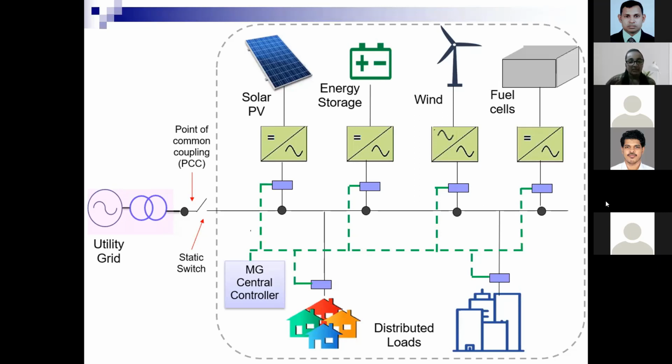And we know when it comes to the conventional grid, large rotating machines introduce inertia to the system such that it will provide extra time for the system to get stabilized in case of disturbance. Since microgrids comprise renewable sources that lack inertia, an energy storage unit has become a necessity. A battery backup or any other energy storage unit in a microgrid functions as a synchronous generator.